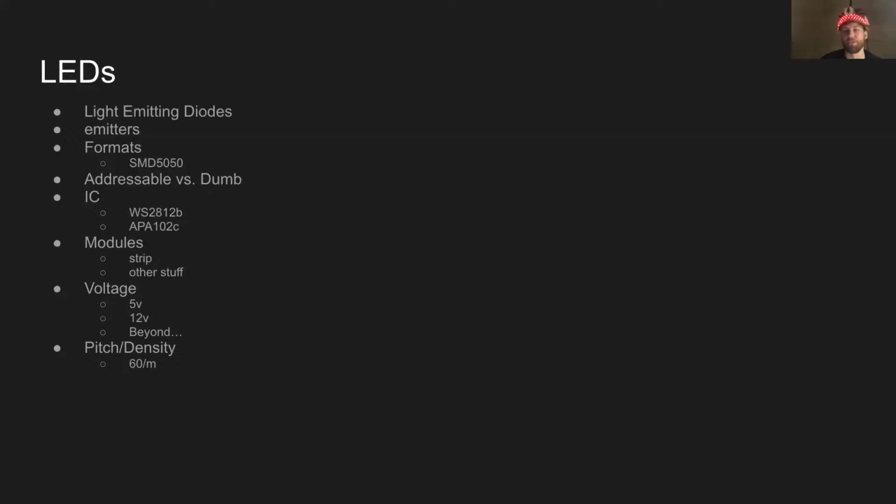In the world of LED strips, there are two conventional densities which you can purchase. 60 per meter, which is this density, which is typically the highest you want to work with. You can get higher than that, like 72 or 144, but the power requirements for that quantity of LEDs become so high that the electrical engineering gets quite advanced, or at the very least, those wearables get very hot. And of course, the materials are more expensive as well.